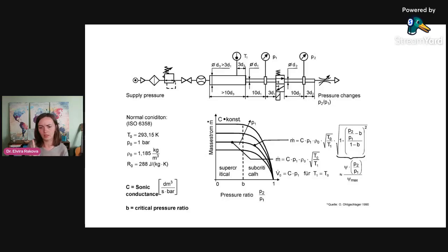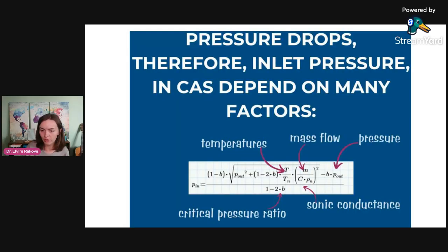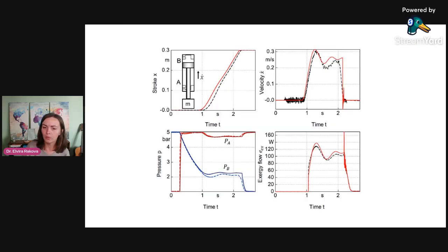And here it is a mind game that you have, because I'll show you now where actually the pipe oversizing plays a role. The pipe oversizing plays the role when we have a demand of the compressed air. So what I mean is demand. You have a point of use where the air is required, where the energy of compressed air is transformed into the mechanical energy of the moving mass, like in the cylinder, or into kinetic energy for blowing applications, for example, right?